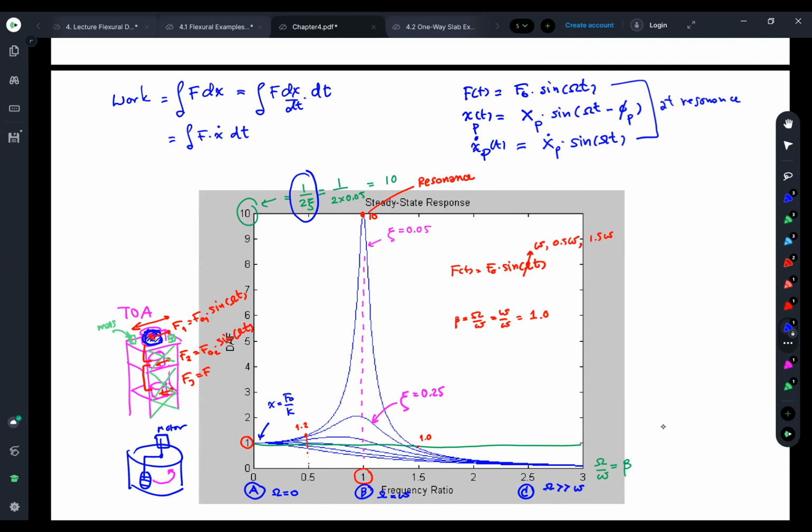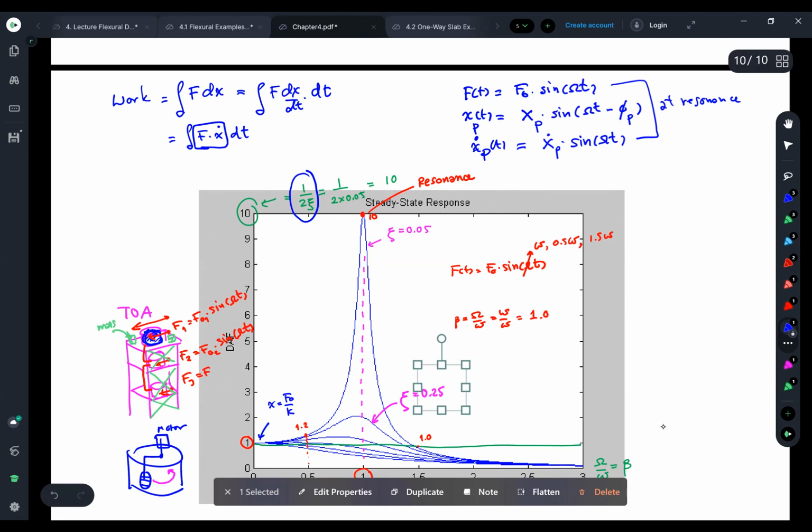If the force is a psi function, the velocity of my building or my structure at resonance, I'm pretty sure, is the same psi function, the same phase of the psi function. They don't have the minus or plus phi p anymore. It becomes 0. This is because we make this term always positive. Remember the sine and cosine, you have plus, minus, and change with time. But if you say this is a function of sine square, the thing is different. The term will always be positive.